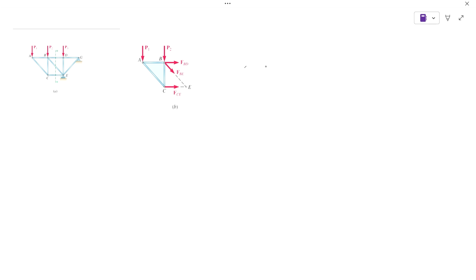Okay, now we're gonna learn about a new concept, which is the method of sections. In the method of sections, when we have a structure with multiple elements, we cut a section, in this case section N, so that we can find the forces internally. So the first step is to find external forces.